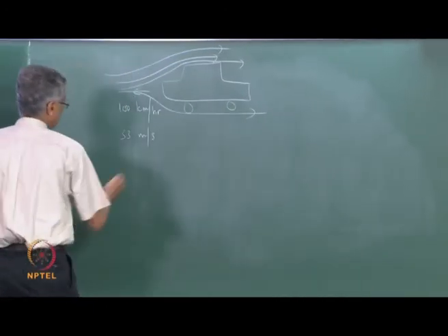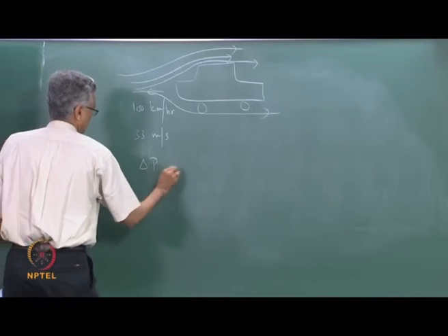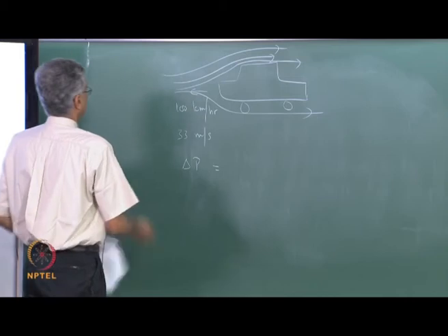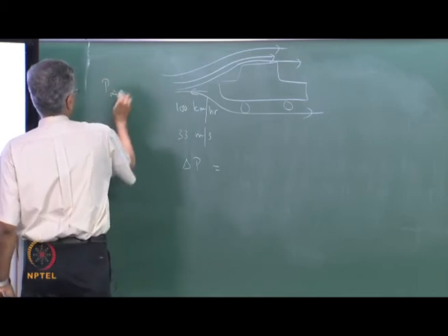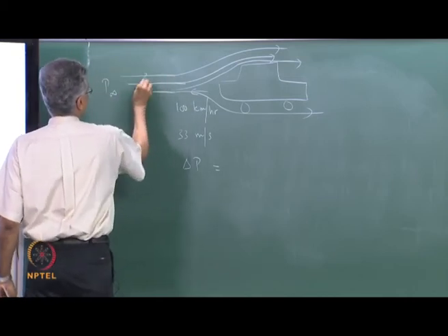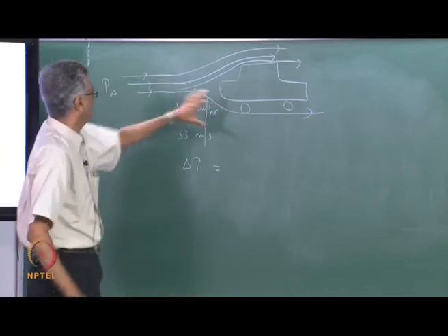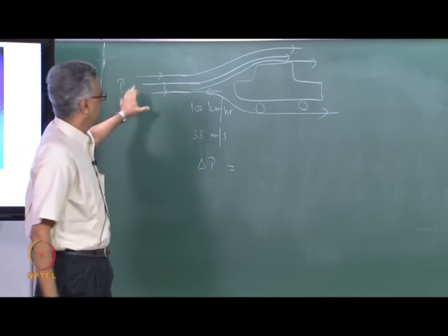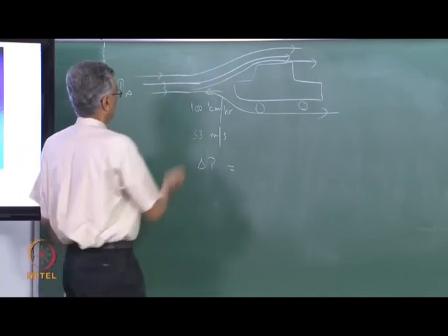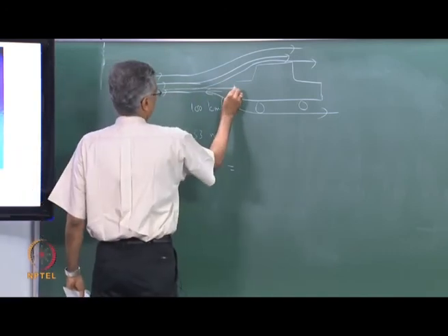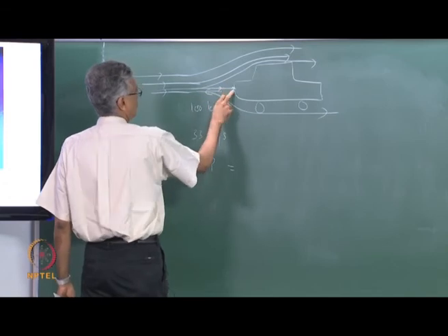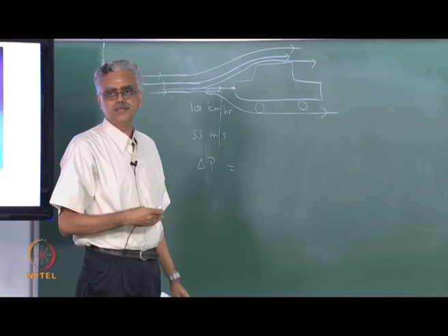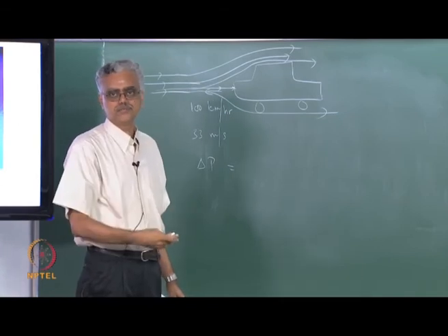Okay, so the maximum change in pressure: the fluid as it approaches is at about a free stream pressure of, let's say, P infinity, right? When the fluid is coming here far away from the vehicle, the fluid is at a pressure of P infinity. As it goes around, there is one streamline, which is the stagnation streamline, where the flow is brought to a halt completely, right? So all the way from P infinity, the fluid is brought to a rest.